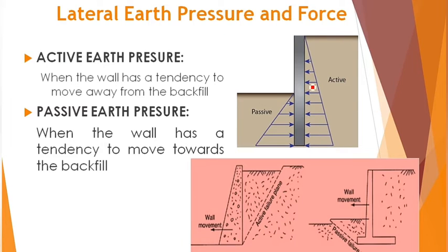If a retaining wall is supporting a backfill, the backfill will obviously provide a lateral active force on this particular retaining wall. This is called active earth pressure, when the wall has a tendency to move away from the backfill like this. This you must have covered earlier.